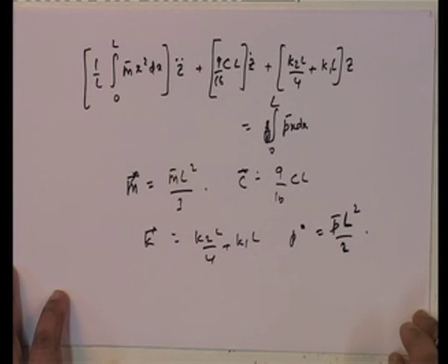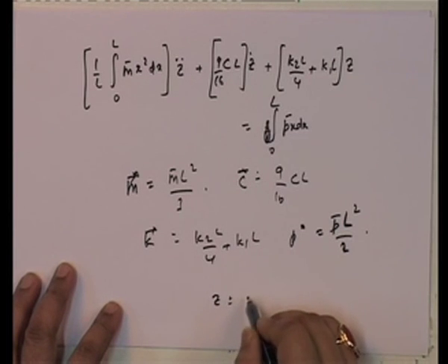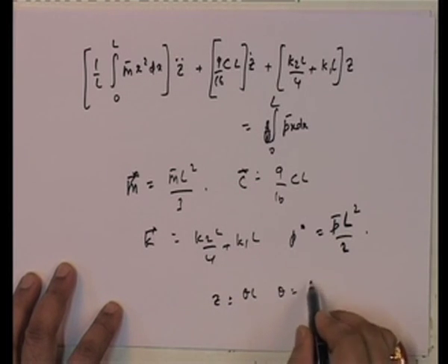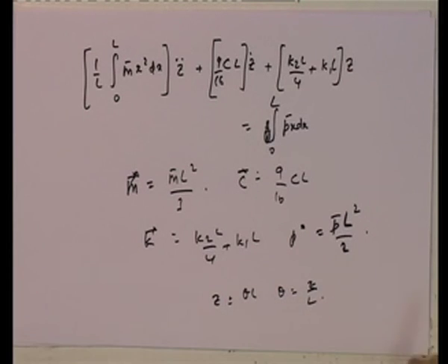Now, you will ask me that this looks different from the other one. Well, if you substitute the fact that z is equal to theta L and put theta equal to z by L, you will see that it is the same equation. So, it does not really matter what we define as our generalized displacement. As long as you have a single degree of freedom, irrespective of whether you take theta or z, it does not matter, you get the same equation of equilibrium.